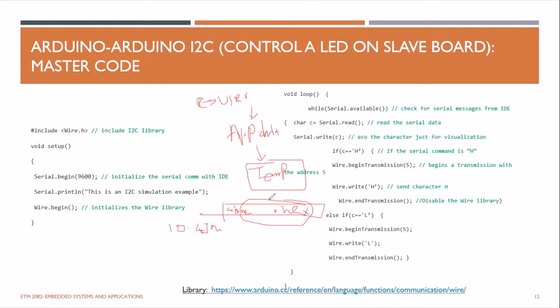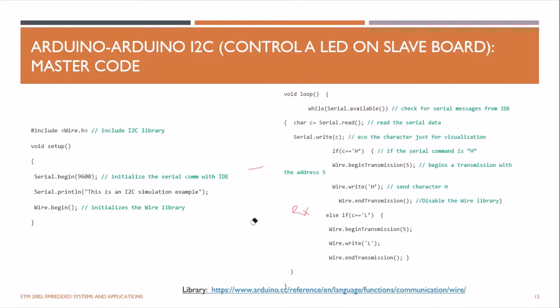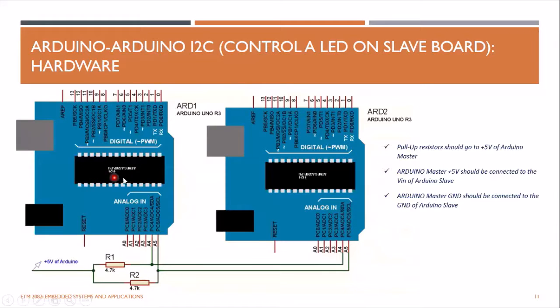because these folders in the temporary location are going to be changed over time. So it's better to copy this hex file and put it on your desktop or something, and then re-import it to the Proteus, right? That's why I want to tell you that when you compile, the hex file will not be generated in the same folder. It is in the temporary folder of your C drive. So you have to import that hex file to this Arduino if you're using Proteus.